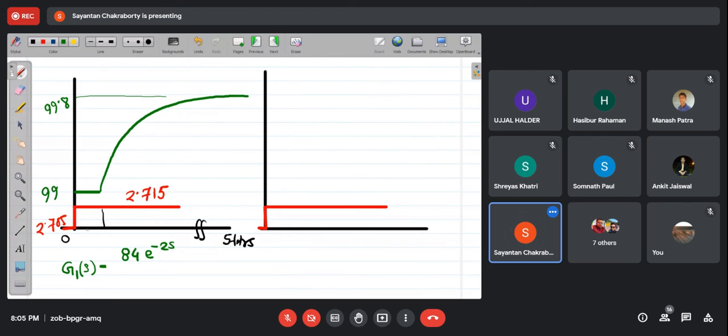This gap is, say, a 2-minute delay. It's not up to scale. So this will be the first order plus time delay transfer function. But to obtain this transfer function, we have to wait at least 5 hours. But instead of that, if you had gone for this integrator plus time delay model, then what could have been done?